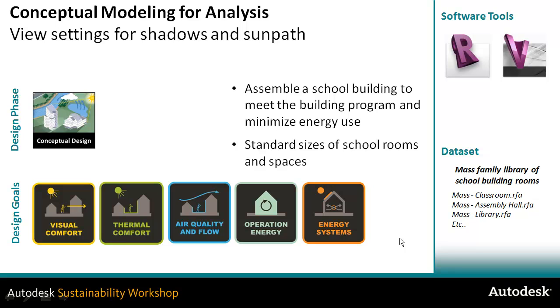So we're going to assemble a school building using typical spaces. The idea here is if you have an architectural reference like AJ Metric Handbook or Neufert's Architects' Data, you could design or draft forms representing a typical classroom and then maybe a typical assembly room. You then take these individual forms, you could use them in multiple projects, but you can assemble different options for the layout of the building itself.